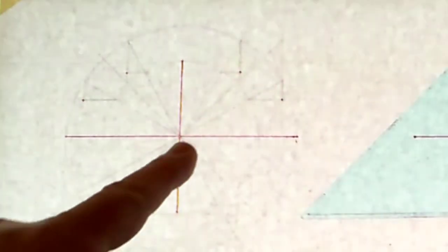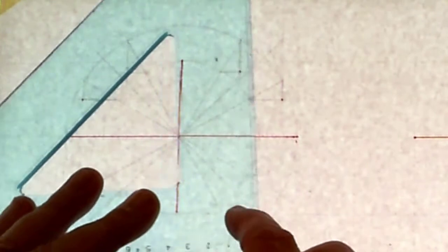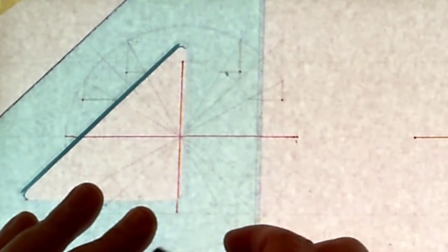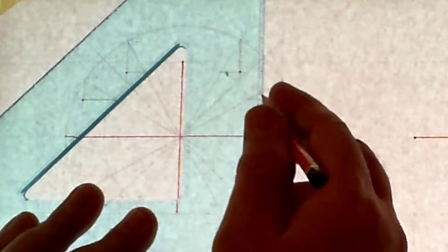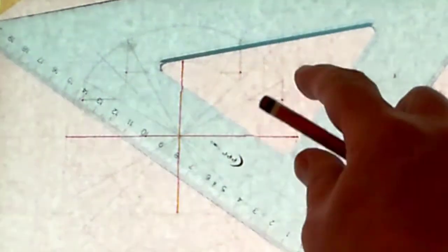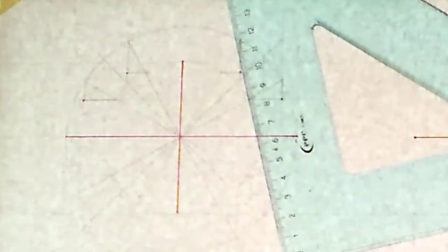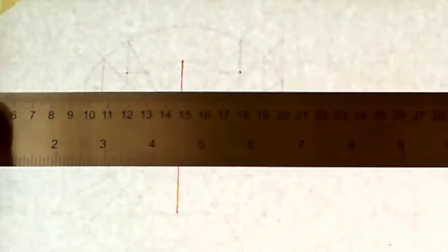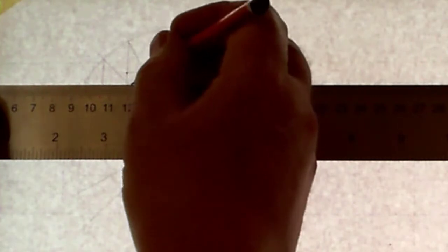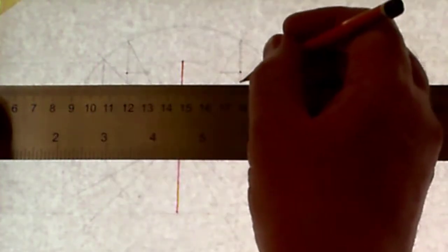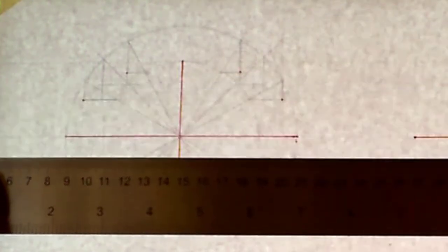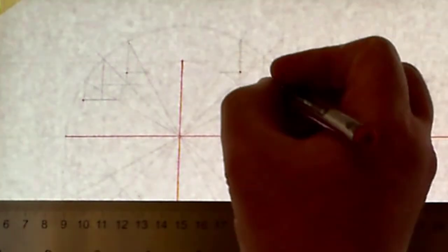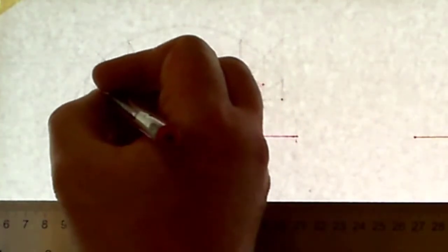Now, that 45 degree line will do the exact same for me. So where it hits the outer curve, I bring down, and do likewise on the other side here, where the 45 degree line hits the outside curve, bring down, and then I bring that 45 degree line where it hits the inside curve out to meet it, and out to meet it here. And I get 2 more points here and here.